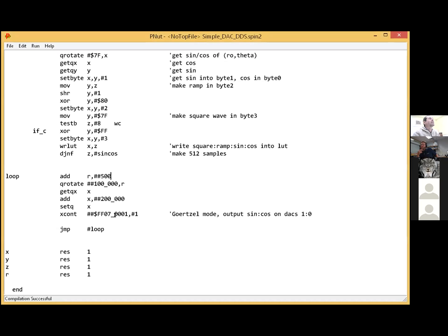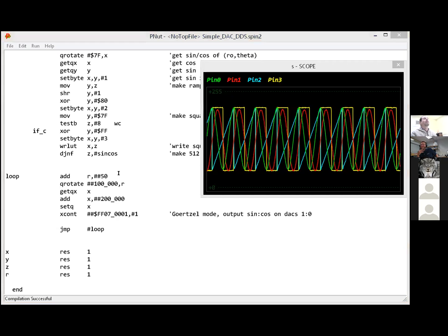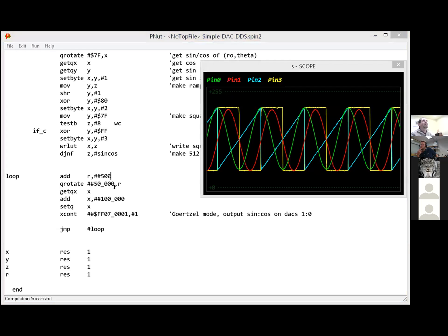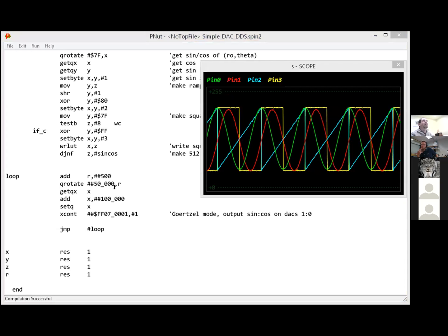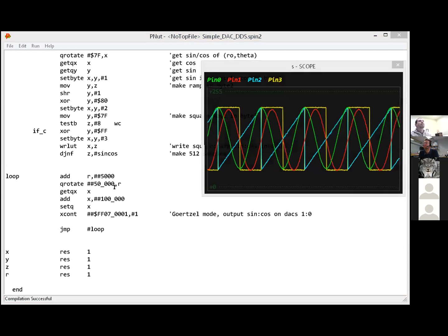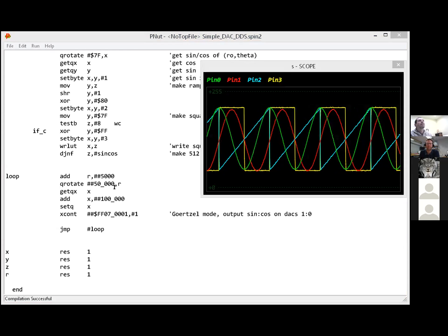So Chip, if it's the filtering, how does the programmer account for that in software? It's just the ADC, the fact that he's reading it back, that's the filter. Right. Yeah, the actual output voltages are going all the way to the top. It's just the ADC scope mode that's sampling it that is filtering it and rounding them off. Right. The square wave is always all the way up there because it's sitting at its peak value for the whole time, and then at the low value for the whole time. Thank you. The ones that are sine or triangle get rounded off.